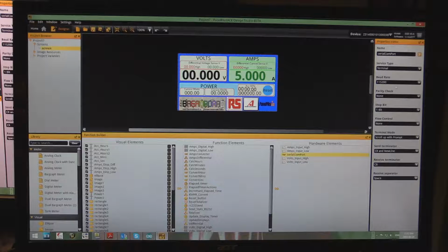If you're outputting a lot of data and you want to do it on a fairly quick basis, then obviously you're going to need to have the higher rating set. The rest of the configuration I left in its default mode, which is no parity, 1 stop bit, no flow control. Terminal mode, I would imagine that's for incoming data, and I haven't got anything to input data on here. Like I said, no serial ports in any of my computers anymore.